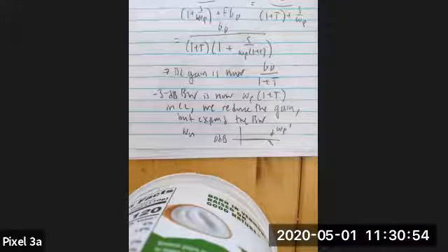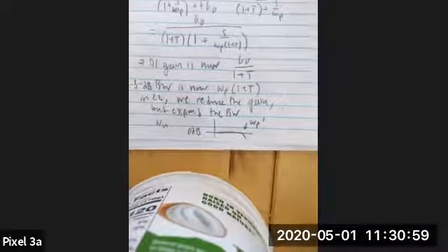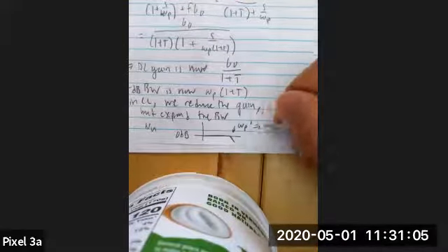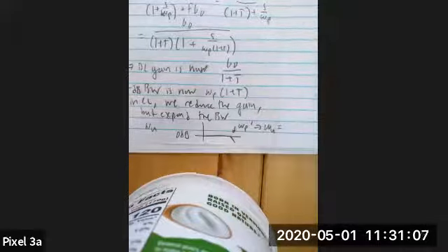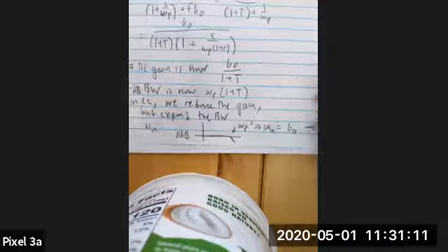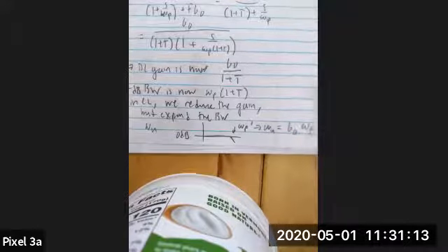So I think the professor would have gone through this in lecture. But effectively, this omega p naught, when this is the case, will be the unity gain frequency of the amplifier to begin with, which will just be the DC gain times the initial bandwidth that we started with. And this is the gain bandwidth product that is approximately constant.